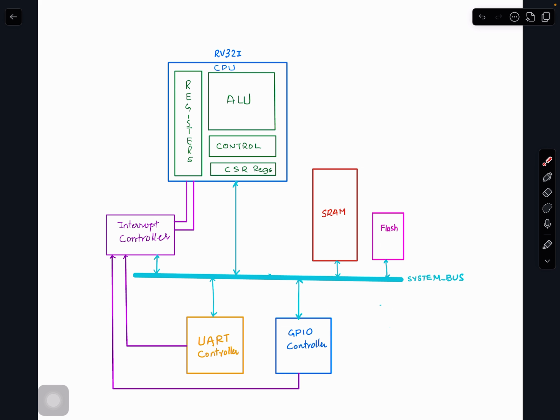This part is within a chip, but still on the PCB, you need to put your instructions into the flash once. And every time power is on, the flash data will be read initially by the CPU. So you have startup code and all that is there. And we will study, when the reset comes, what kind of operation happens in order to start, initialize everything and have the processor ready to execute. But our basic code will come from here. It can be copied later on here and processed from here, but initially it will be here. So flash needs to be connected.